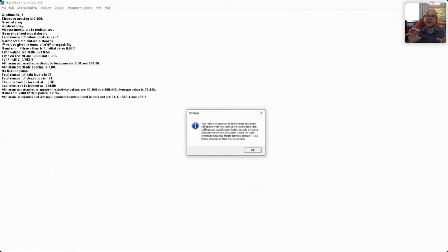So when we looked at that diagram of cells that the software uses to build the model, this is saying, well, if you put more cells across the model, then that allows me to vary the resistivity in the model more smoothly, and I can probably cope better with this fast changing data set that you've loaded.